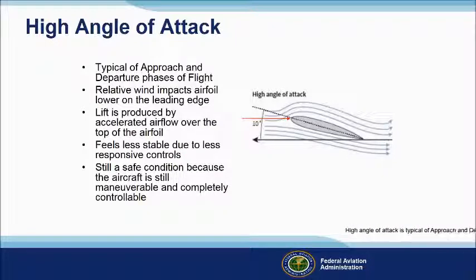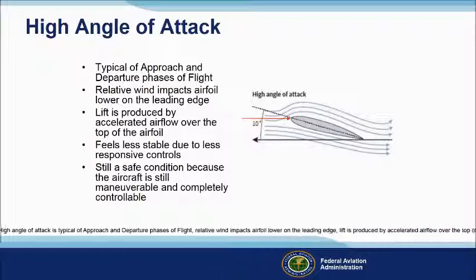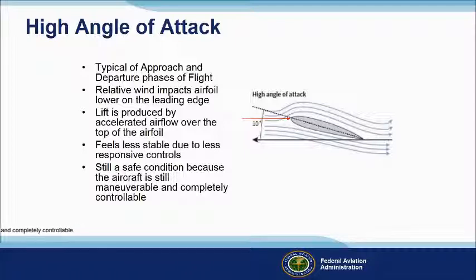High angle of attack is typical of approach and departure phases of flight. Relative wind impacts the airfoil lower on the leading edge. Lift is produced by accelerated airflow over the top of the airfoil. It feels less stable due to less responsive controls, and is still a safe condition because the aircraft is still maneuverable and completely controllable.